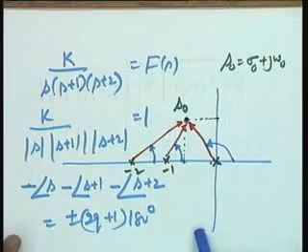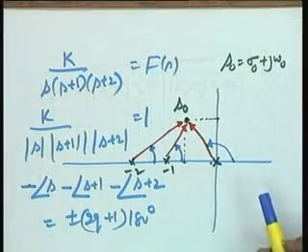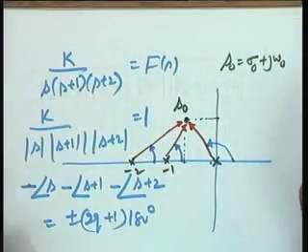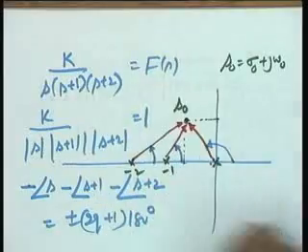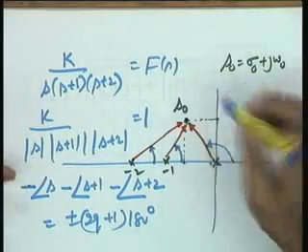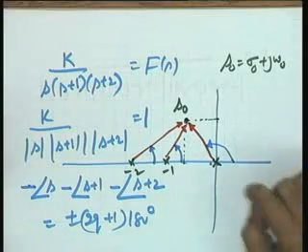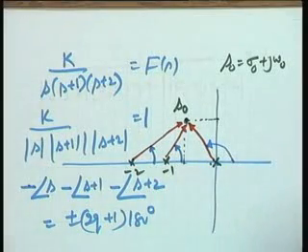So you have to see this particular angle, and the total angle contribution at this particular point gives you the angle criterion. If both these conditions are satisfied, you will say that this point meets the magnitude and angle criterion and is therefore a point on the root locus plot. Okay. This is definitely a point on the root locus plot in that particular case, right. Now can I ask you my question?